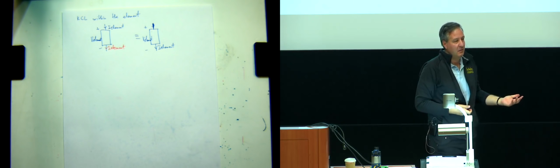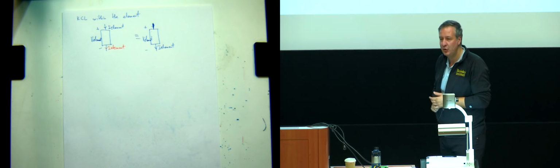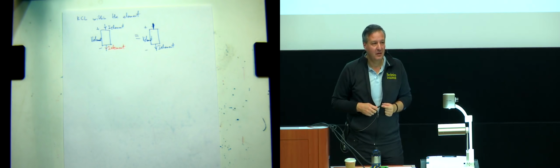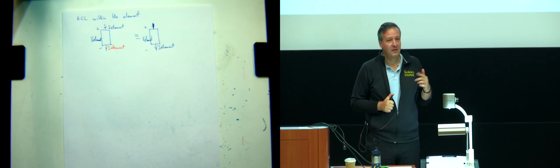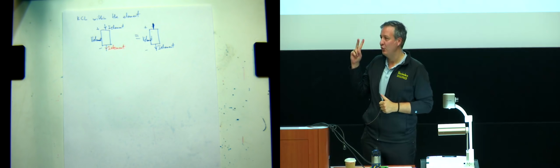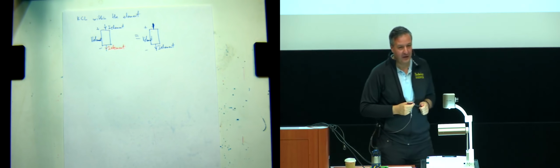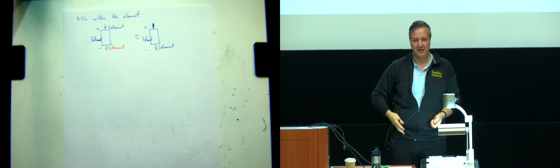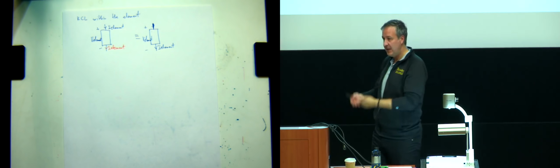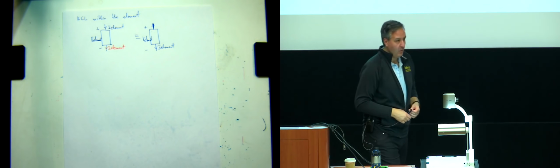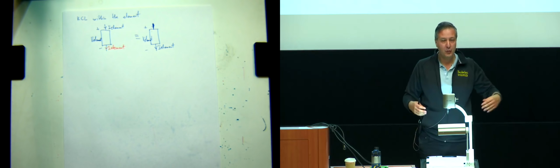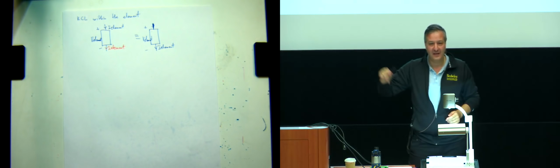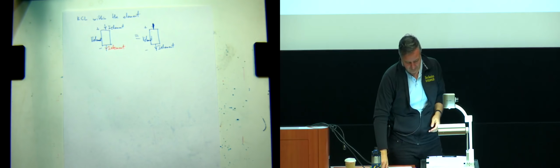How do I know that? Which rule applies within the element? Anyone? We only learned 2 rules, so you have a 50% chance of hitting it. KCL, right? At any point along the element, there is some junction of some materials or something, so for every piece there, the same KCL applies. So don't assume that some current goes into the element, but an explosion of current comes out of the element, or like 10 times that current. No, the same current flows through every element.